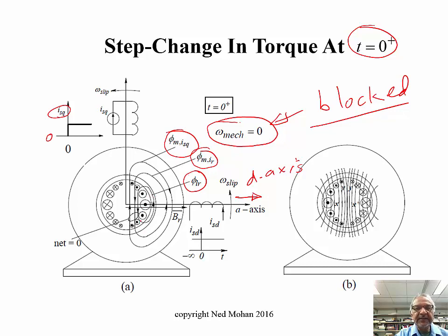The bottom line is that the net of all these three flux lines, one due to the stator current, one due to the rotor bar currents, whose flux distribution is reaching the stator, and the third one is leakage, all three combined is equal to 0. Okay.